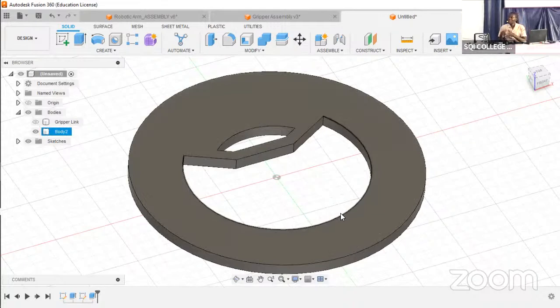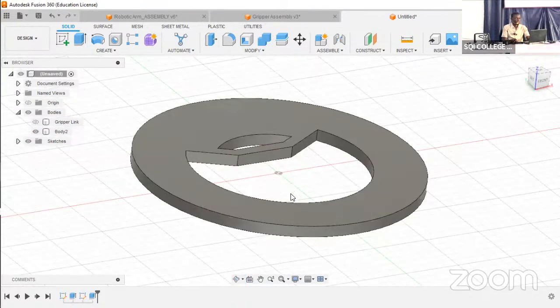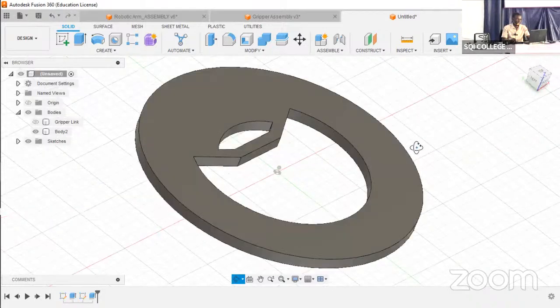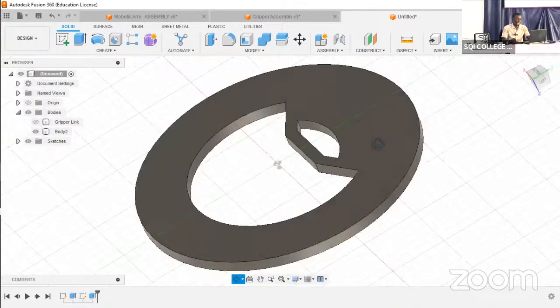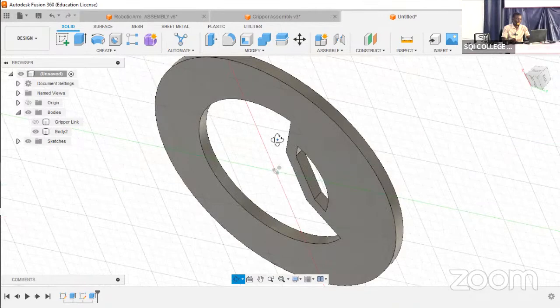All right, so for those of you that have a mouse, there's a better way you can orbit. Instead of coming down here, click on this orbit tool and turn it around. Press escape. Hold down the shift button on your keyboard. Now there's a button on the mouse wheel. Press that button down. The moment you press it, you can see your cursor has changed to the orbit cursor. And now you can drag around, the front, the back, the sides.